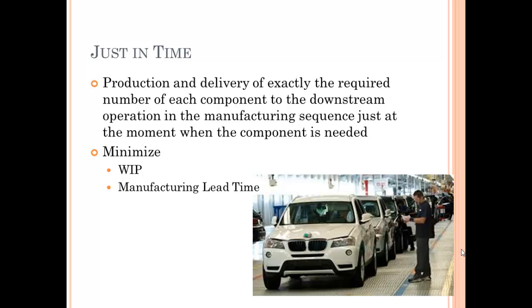It's when a component arrives where it's needed, exactly when it's needed. And so what happens is it doesn't get there before, you don't have an excess inventory. It is the next workstation that determines what the production in the previous step is going to be. It minimizes WIP, that's work in progress, and manufacturing lead time.